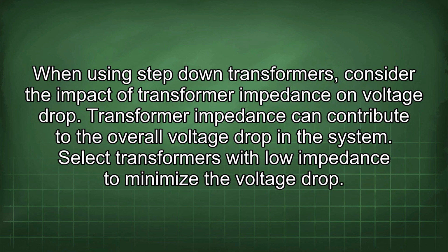When using step-down transformers, consider the impact of transformer impedance on voltage drop. Transformer impedance can contribute to the overall voltage drop in the system. Select transformers with low impedance to minimize the voltage drop.